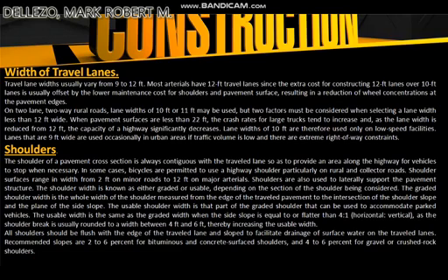All shoulders should be flush with the edge of the travel lane and sloped to facilitate drainage of surface water off the travel lanes. Recommended slopes are 2 to 6% for bituminous and concrete surface shoulders, and 4 to 6% for gravel and crushed rock shoulders.